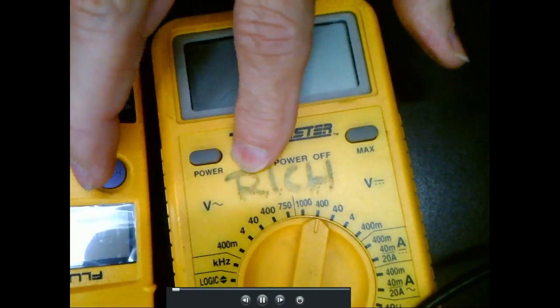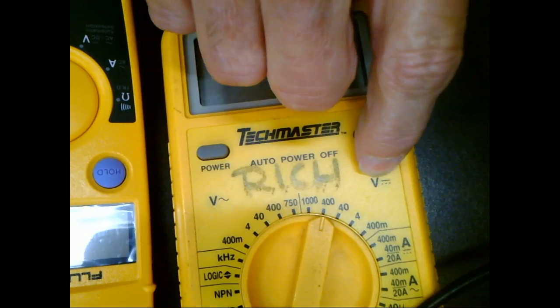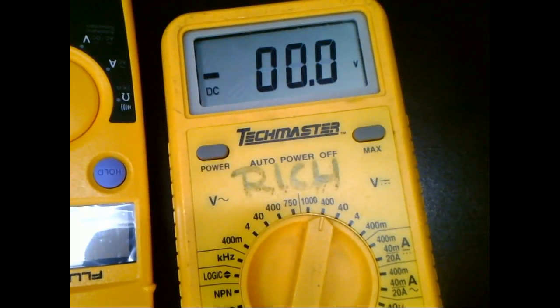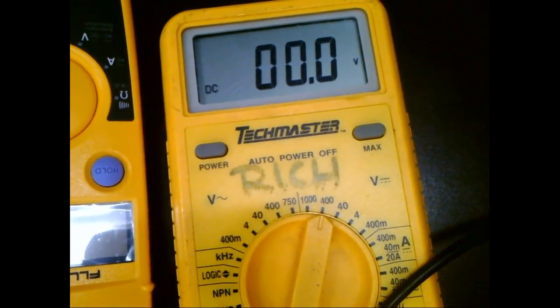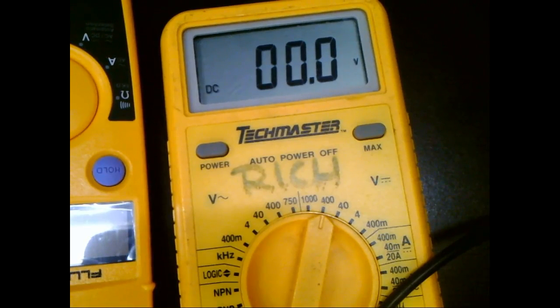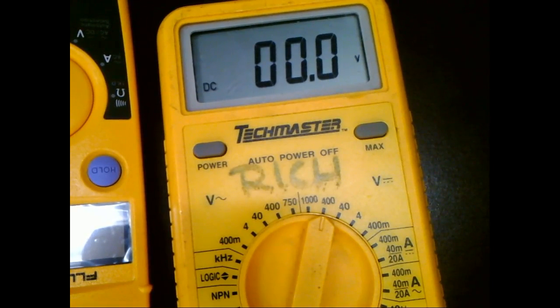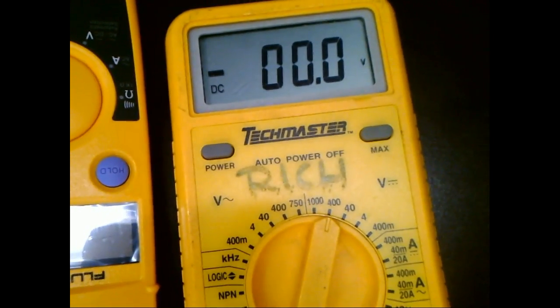So I've got my meter on DC. That's the symbol for DC right there, right? I've got it on the 400 volt scale, and I'm going to turn it on and put it in this outlet. There's definitely power on this outlet, right? What's it going to measure? It's going to measure 0. Why? Because this is an average of a cycle. The DC average of a cycle is 0, because your positive alternation and your negative alternation are canceling each other out.